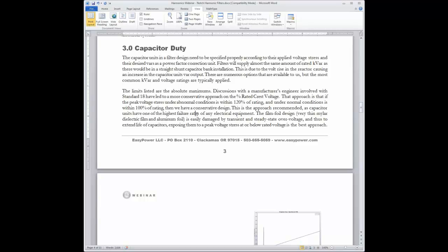The capacitor is typically created by thin mylar, dielectric, or paper, and it's very thin. If it's mylar, it's typically impregnated with oil. I'm speaking mostly about medium voltage capacitors. Since it's so thin, its main mode of failure is dielectric failure. To make sure we cover for that, we take the rated voltage of the capacitor for whichever one we've selected, and we could do a square root of 2 factor and start adding up all the peak voltages, but you can do it in RMS too. It's kind of the same thing.